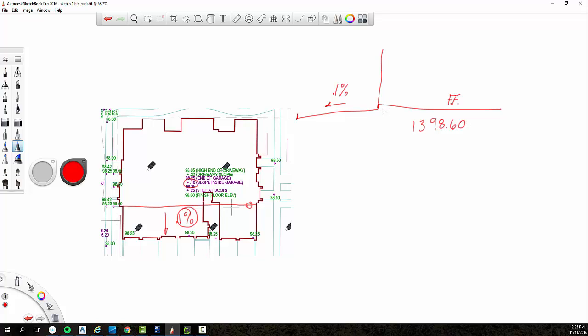And then what we'll do here is we're going to drop this down that 1/4 of a foot, and then we're going to project that out at 0.1%. And within this area here, I'm going to show us how we can use a grading object to attach to this 1/4 of a foot low feature line from the finished floor, and then we'll grade that out using a grading object, and it'll create a small surface of this area here, and then we'll pick up some of this line work here.